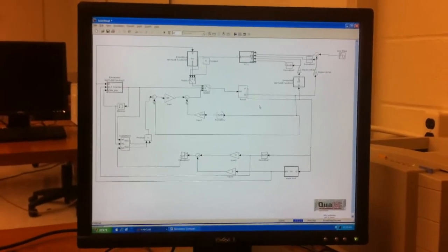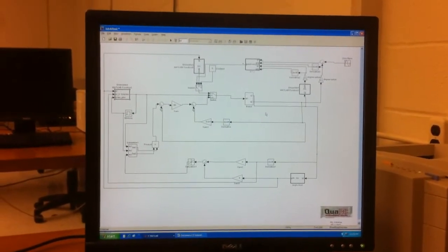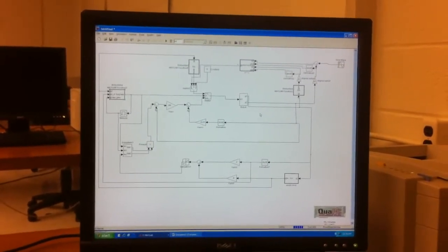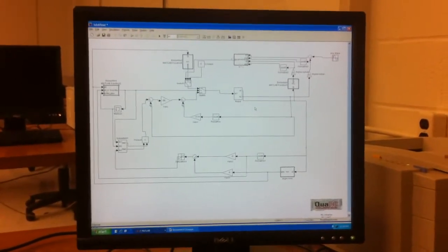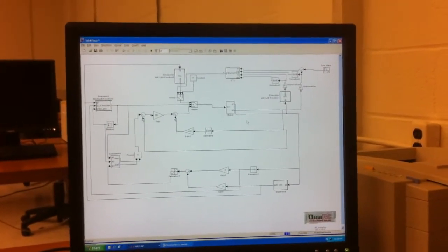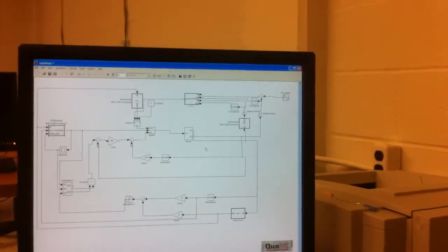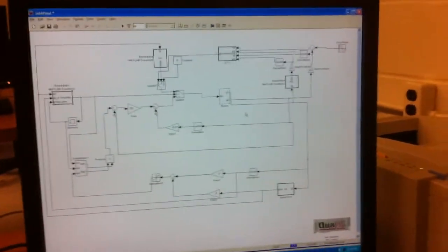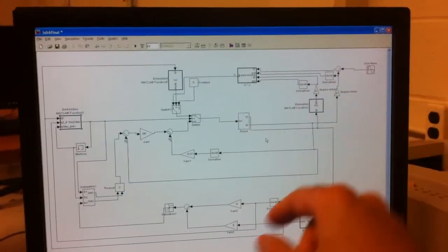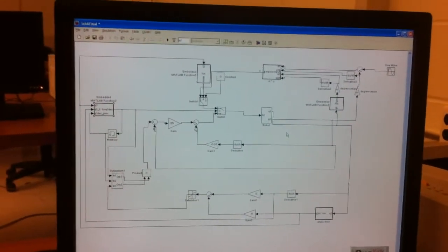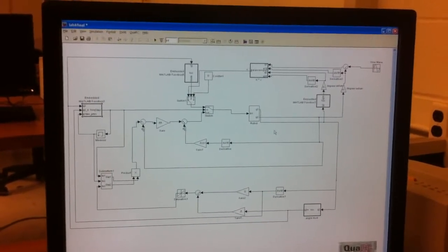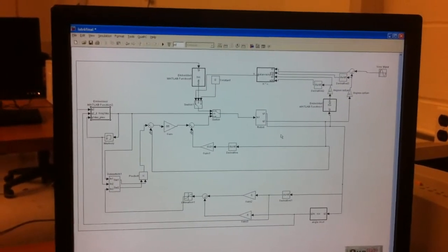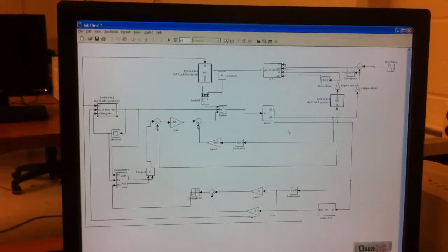So the other part of the control system that we built was for the balance mode. So once the swing up is complete and it gets to plus or minus 165 degrees, the angle of the pendulum, the swing up mode gets switched off, and we turn on the balance mode, which in order to derive that control system, which is shown up here, we made a state space model and linearized it around the vertical pendulum position as angles Q1 equals 0 and Q2 equals 0.